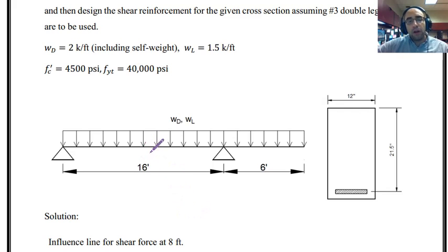Over here, I have this point, and I'm going to consider the influence line for shear at this point. For that, based on the things that we learned from structural analysis, or based on Muller-Breslau's method, I have to consider a cut like this, and I have to make sure the slope is not different from the left side to the right side. The only thing that I'm going to change is just a unit deflection or deformation. For that, we can draw a diagram like this.